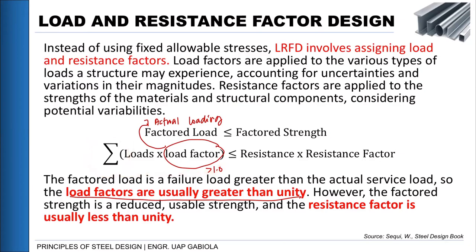It means na for every load type na meron tayo, let's say for example, dead load, live load, wind, earthquake, and so on and so forth, these loadings have different load factors na ginagamit. Let's say meron siyang load factor for dead load, factor for live load, for wind, and for earthquake. And then what we do is we try to have a combined effect of all of this loading and then try to compare it with our factored strength.